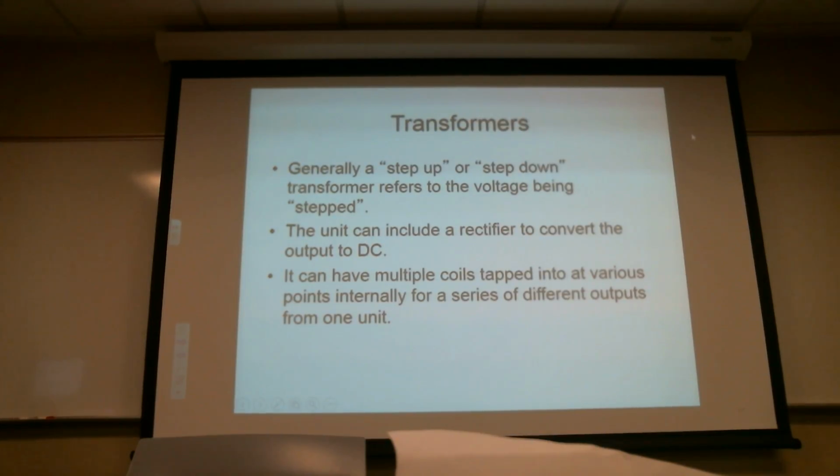Okay. I may also design it to include an internally installed rectifier. So I may make a nice little power supply unit that not only steps up or steps down, but then converts it to DC. So on the output end of this thing, one end's designed to plug into the wall, the other end's designed to put out 12 volts DC. And in fact, I could package it all up, put some filters and do a bunch of other things, and sell it to you when I sell you your laptop. Right? Put it in a little hockey puck there and put a nice little wire coming in, a nice little wire coming out, label on the bottom.